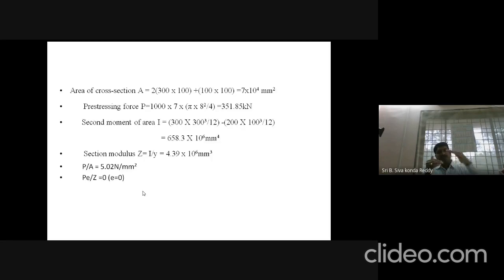This is the reason why you see pre-stressing cables at two extremities in our cross section. Whenever you calculate the centroid of that pre-stressing steel, it would be exactly at the center of our given I section. Eccentricity is the distance between CGC, center of gravity of our concrete, and CGS, center of gravity of our steel.